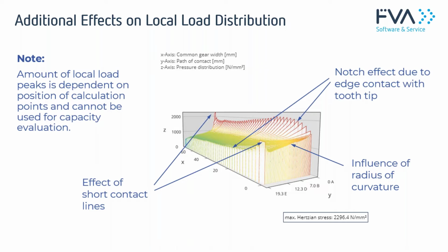Because you can imagine, maybe due to plastic deformation at this position, or to some wear or some small pittings which you get at these edges, and then when outside of this area the load is not so high, no bigger gear damages will start from these load peaks.